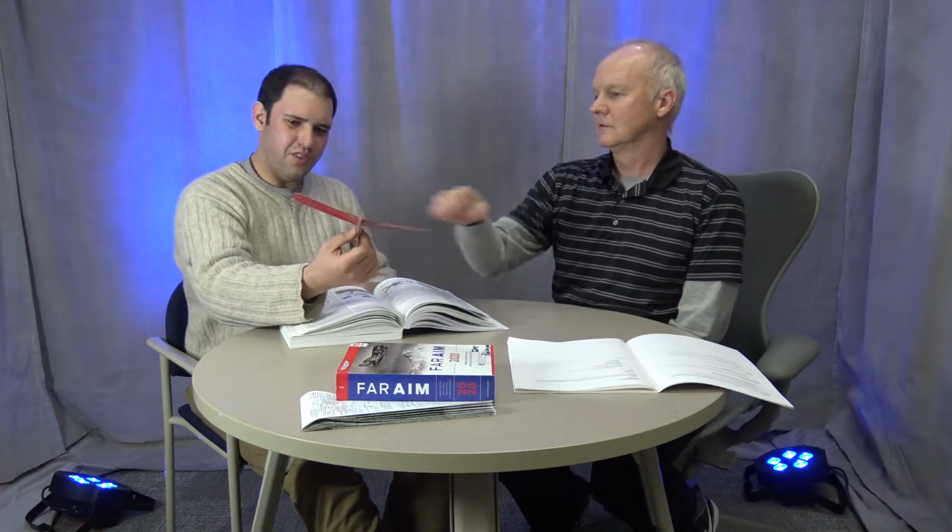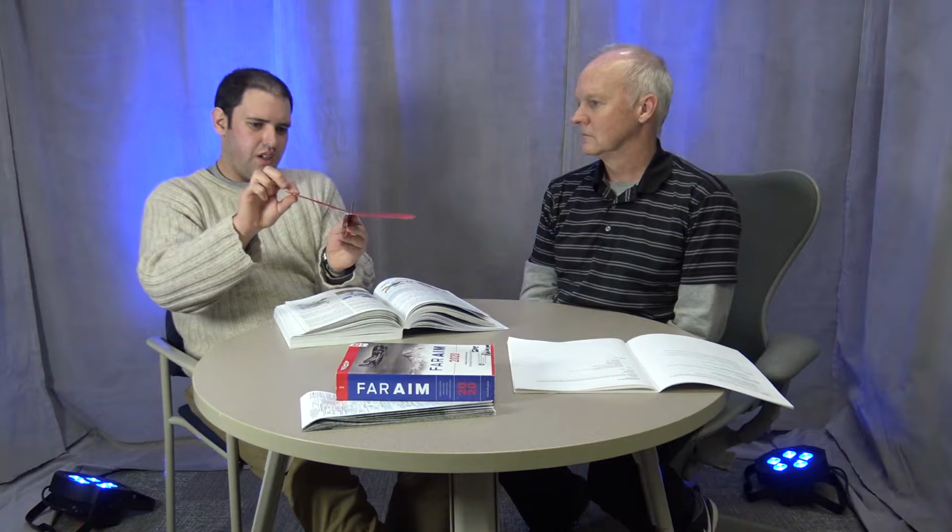When you do that, though, we talked about how creating lift creates induced drag. So when the aileron moves down, that creates more lift to push the wing up. It also creates more induced drag, so it pulls the wing back. So when the wing lifts up to turn the airplane, it also pulls that wing back, which pulls the nose towards the outside of the turn. So when we roll into a turn, we have to add rudder into the turn to counteract the fact that the aileron, which is pushing the wing up, is also pulling us towards the outside of the turn. That's called a coordinated turn.